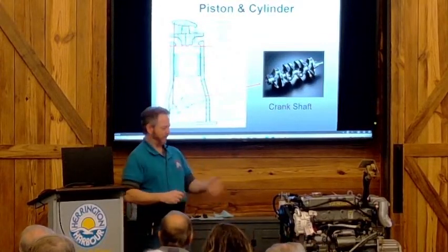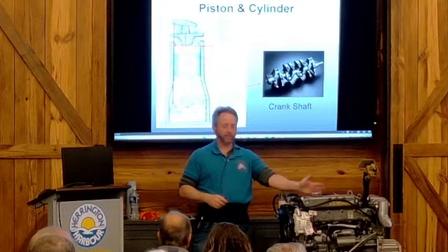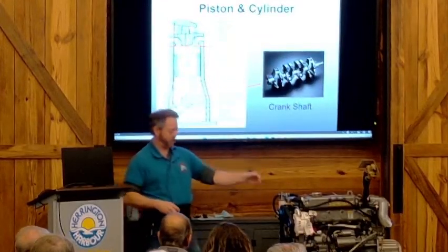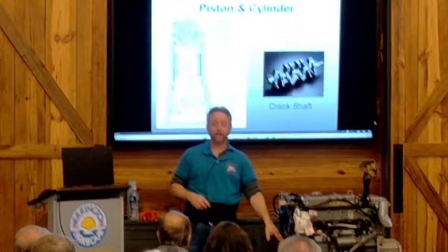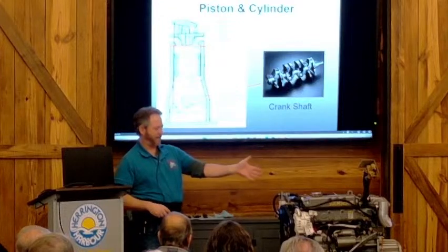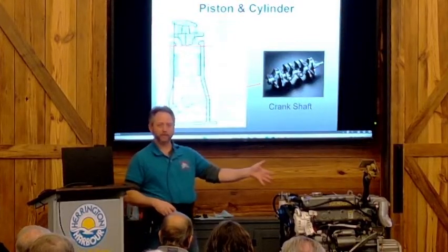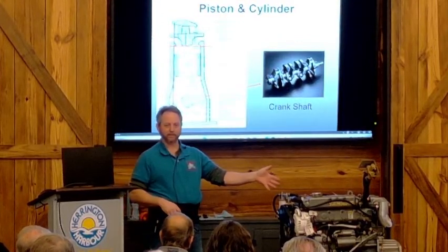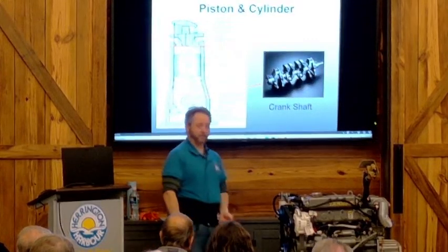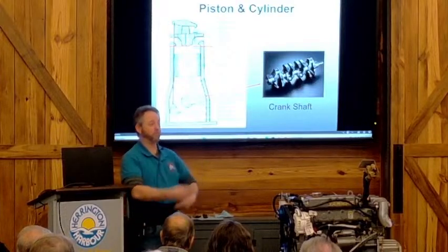And so this is a 75 horsepower engine. This engine's developing 75 horsepower because it's turning the engine to 3,800 RPMs. But I can have an engine the same size produce 150 horsepower, and it's only turning 2,800 RPMs because it's developing more torque.